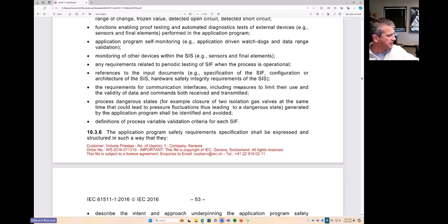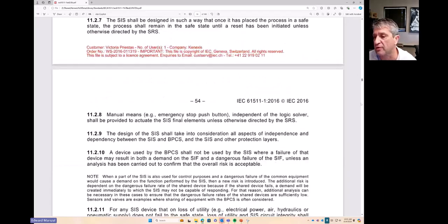that's in one of these documents. These guys, OREDA, tend to get a lot of credit for being the ultimate source of truth. But what you're going to see when I go through this process is that picking a failure rate is more of a research activity, where you're finding clues about reliability data in multiple different places and trying to resolve all of the conflicting data that you're getting from multiple different sources to come up with a number that's actually going to be relevant to what you're doing.